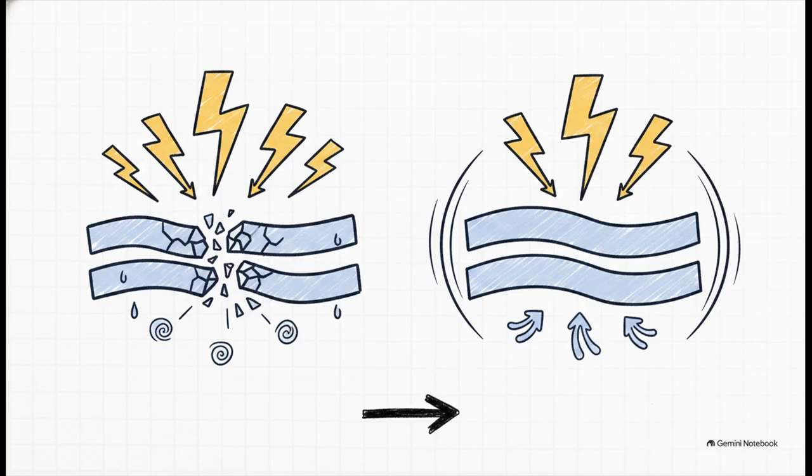But silicon definitely has its limits, particularly when handling high voltages and high temperatures. And that brings us to an absolutely massive breakthrough: wide bandgap technology, specifically gallium nitride, or GaN for short. GaN has a significantly larger forbidden energy gap than silicon. Finding materials with these wider band gaps is the absolute secret sauce behind the current revolution we're seeing in power electronics. A wider band gap means the material can withstand much higher electric fields before breaking down, and that allows for faster switching and dramatically lower energy losses.